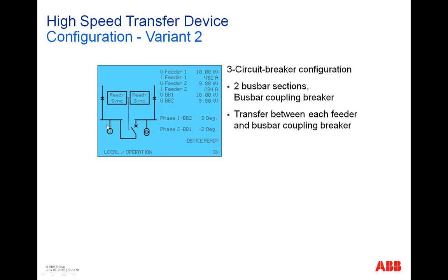That means you can give a load shedding signal to main motors or something else which are not so important for the connected process. And then in the moment of transfer, you can disconnect some unimportant loads so that the second incomer can provide energy to all the other loads.